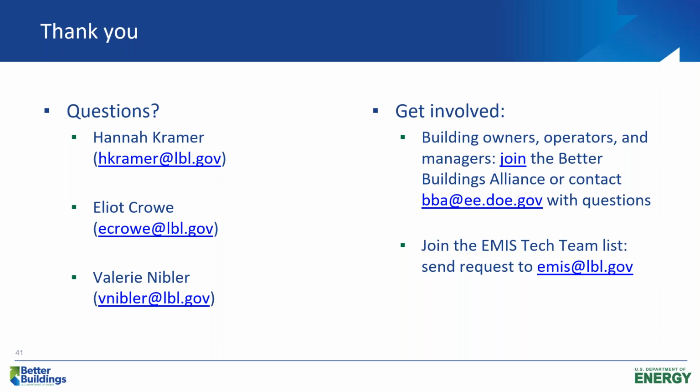Great, great. Next one, this is a good one. We don't have a building automation system. Can we still do FDD? Yeah, I didn't talk about that too much. We had been talking about BAS being the main data stream to FDD. There's also FDD for what's generally called an advanced rooftop unit, where they have some FDD algorithms built into the controllers in the advanced RTUs. So that's another way, if you don't have a BAS, that you can still do FDD.